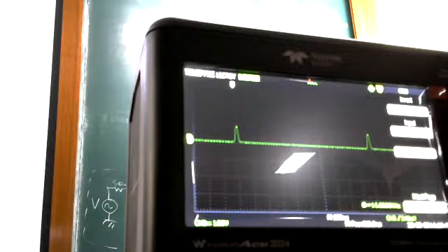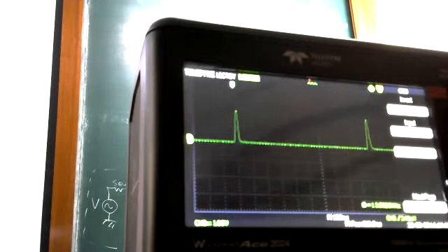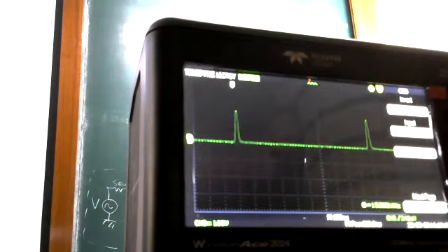I'm going to leave it at 1 mega ohm because it's actually convenient for this particular demo, because I can now probe this area without changing too much about what's happening with the rest of the transmission line, right? So we will leave it at that and then make some changes to this and see what happens, okay?